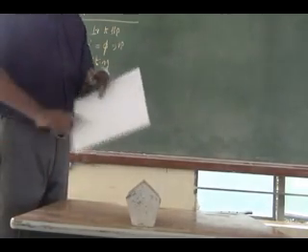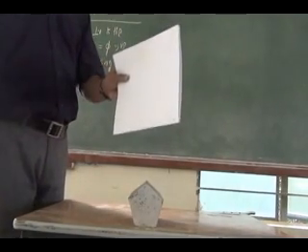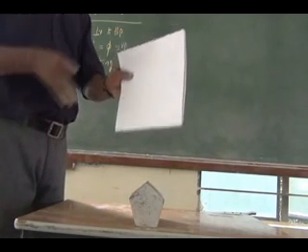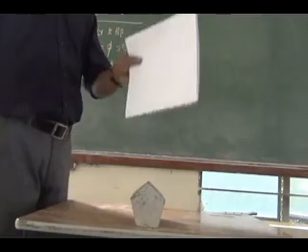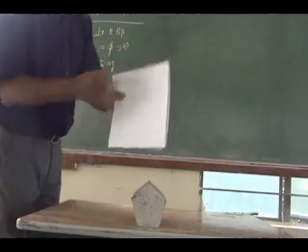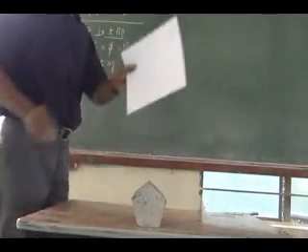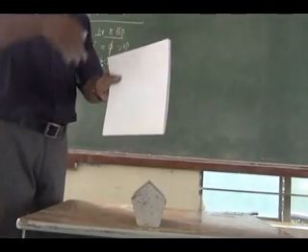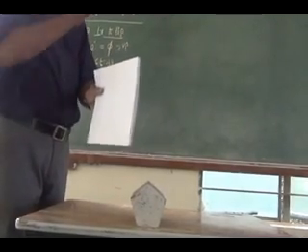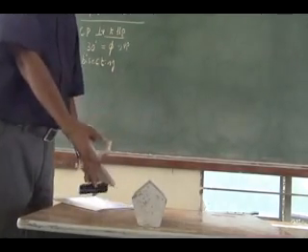Right. Now you tell me where I have to represent the cutting plane, in HP or VP? HP, since the cutting plane is perpendicular to HP. So I have to represent the cutting plane on HP. That is nothing but my top view. Then you have to move on to your sectional front view, then the true shape. So quickly you draw the projection.